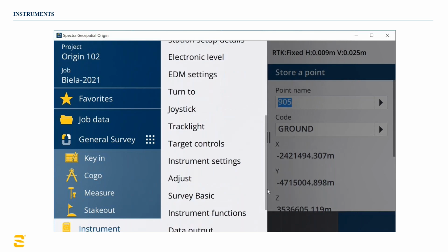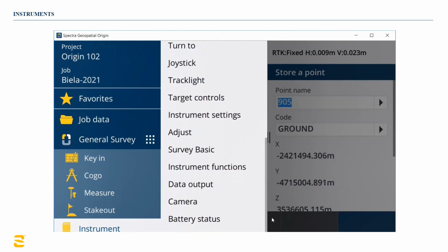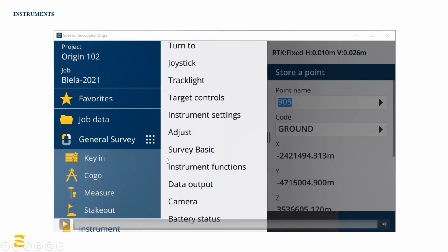I'm not sure what, to me, ECEF is the same as Cartesian XYZ. So I'm not really sure what we're talking about as far as a difference there. In the ITRF, that is a function not of the display, but of the coordinate system that's being defined, right?